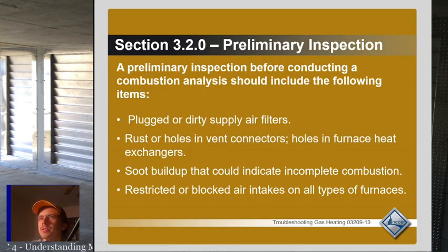A preliminary inspection before conducting a combustion analysis should include the following. You want to look for plugged or dirty supply air filters, rust or holes in vent connectors, holes in furnace heat exchangers, soot buildup that could indicate incomplete combustion, and restricted or blocked air intakes on all types of furnaces. So basically, you want to make sure that this test is going to be accurate and there's not any glaring problems that are going to mess up your results.